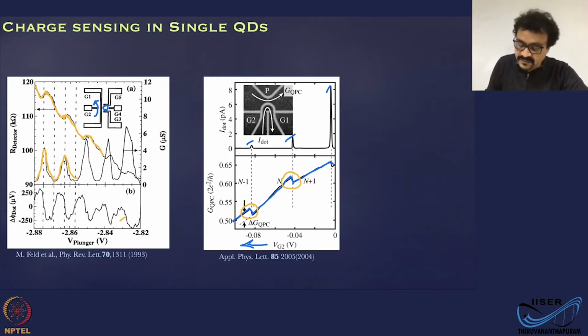So that is not affected by the negative gate voltage, but the current through the dot, you can see that is greatly affected by the tunnel rate, and that it goes down drastically as the gate voltage is made more negative. You can see this peak height, that the Coulomb blockade oscillations goes down drastically as the gate voltage is made negative.